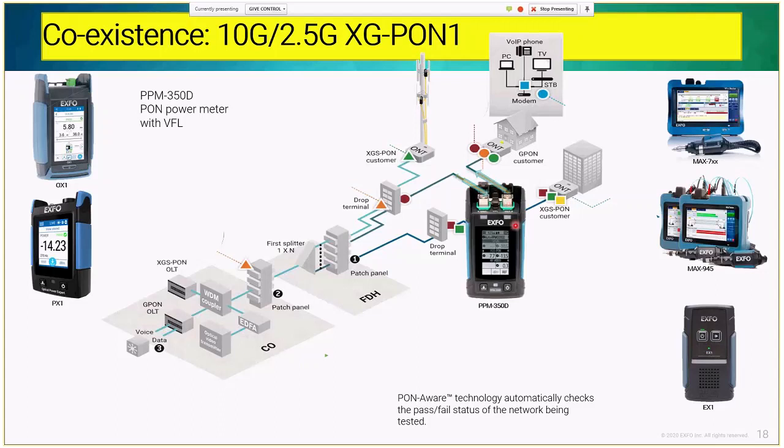And with the PON power meter, you have your port where the signal comes from the OLT into the unit and the ONT going into the unit. You have as well your VFL port, which can give you the possibility to detect some macro bends inside of the customer house. These can be used just before the customer house, just before the drop, and also can be used in the customer house just before the ONT. If you don't need to measure the upstream layer, you can always measure only the downstream layer, so the downstream from the OLT, disregarding the ONT side.